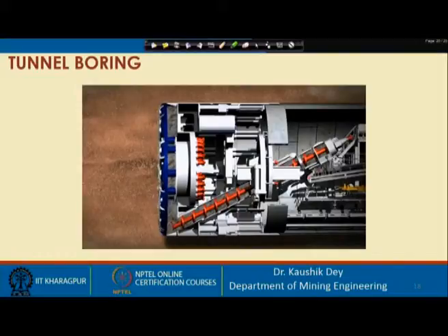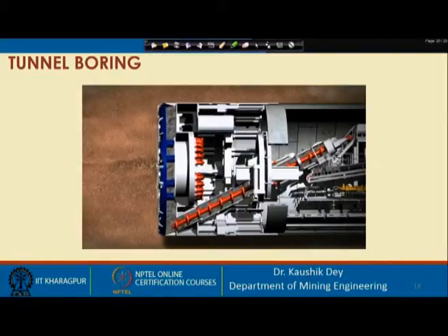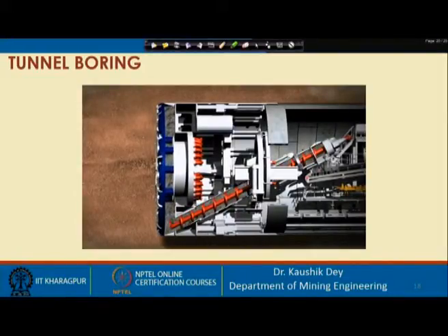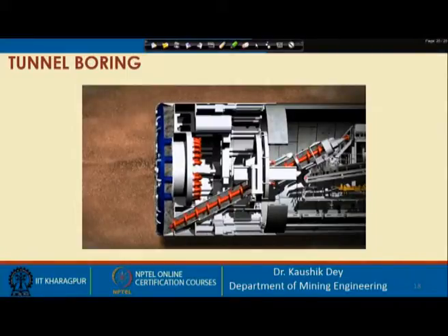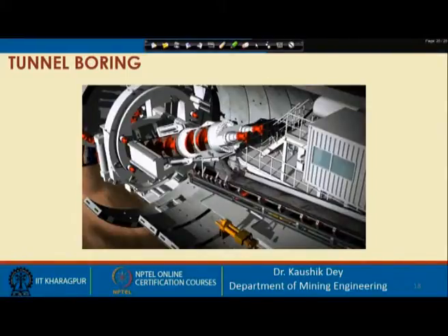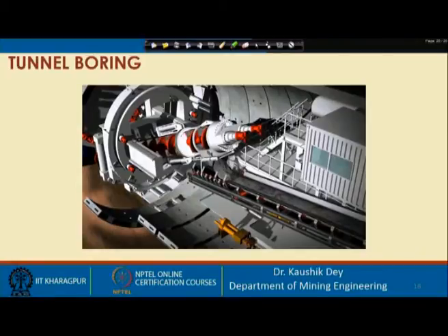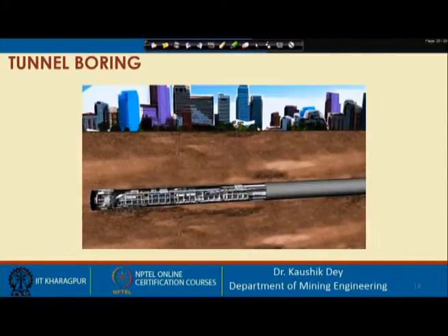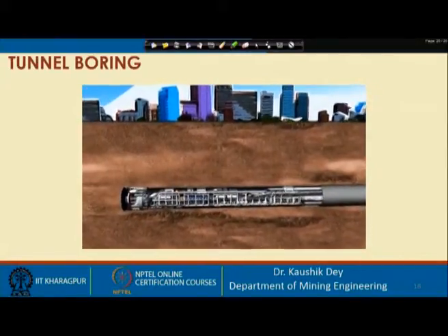The tunnel face is continuously monitored by pressure sensors. They check the turning time of the cutting wheel and the screw conveyor, and they also keep track of the material that has been excavated. The belt conveyor is telescopic, and that will be extended in time to time. So, you can see as the cut material in slurry form is being transported through the belt conveyor.